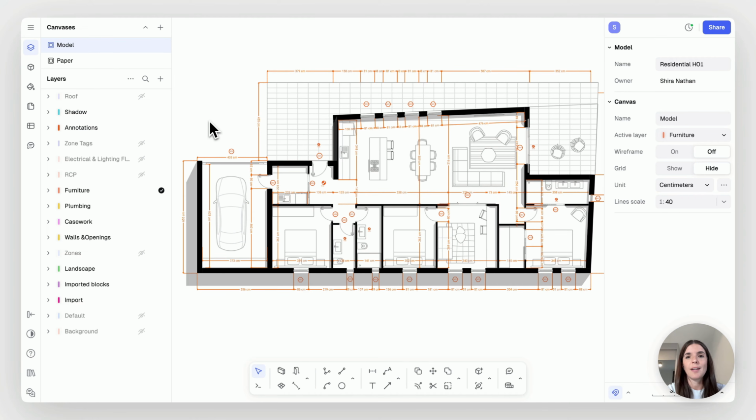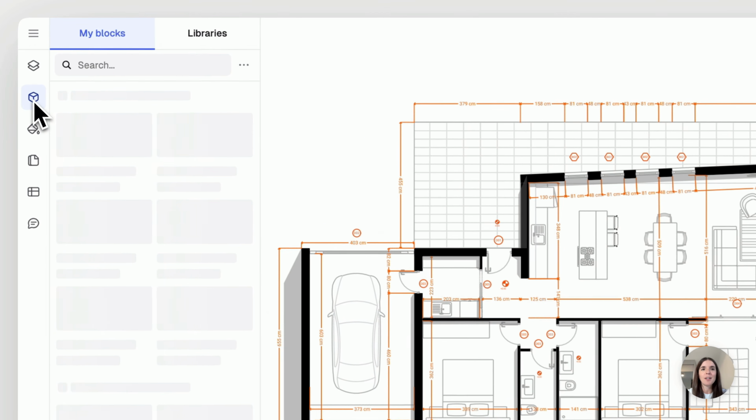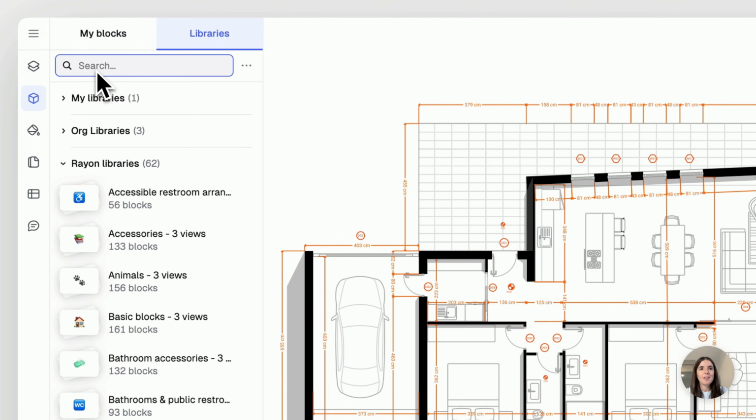We're going to draw a line on the floor plan that will indicate where our section is going through and what spaces we're going to see in the sections, what are the relationships between them. So the first thing to do that is to use a section symbol. And for that, I'm going to take us beneath the layer panel to the block panel, and you'll find Ryan's block library. Ryan offers thousands of different blocks from different use cases.